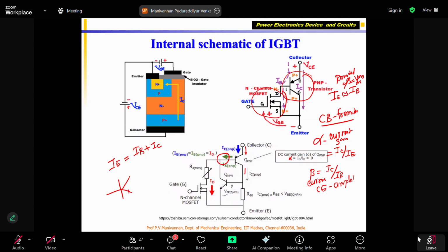Again, I will draw for you to understand quickly. I give voltage to my VC. This is my plus minus VCC. I am giving here VB. I have a resistor here. I have a resistor here. This is called RB. This I call RC. This is my emitter, collector, base, NPN transistor. We know that this current is called IB.